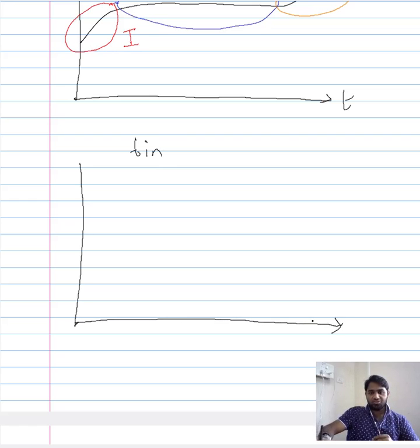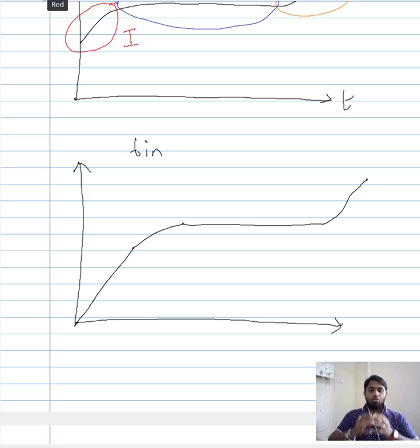So instead of a 3-staged one, you can treat that as a 4-staged one, wherein the first stage would be the instantaneous creep, the second stage would be the transient creep, the third stage would be the steady state creep, and the final stage would be the accelerating creep. If you want a more generalized representation of the creep, a creep curve that is independent of the time taken for the instantaneous creep, the way to achieve it is by splitting the curve into 4 stages.